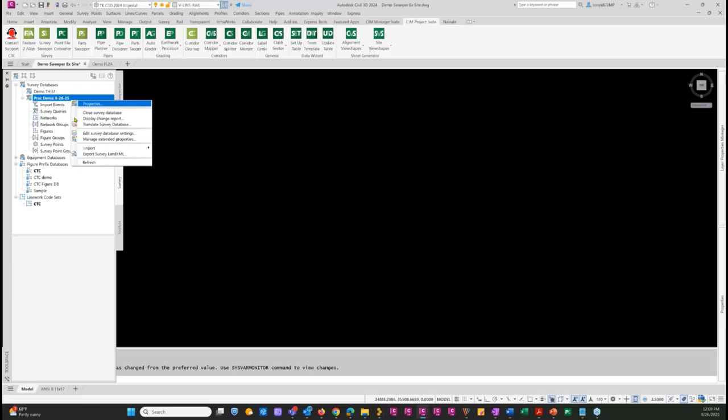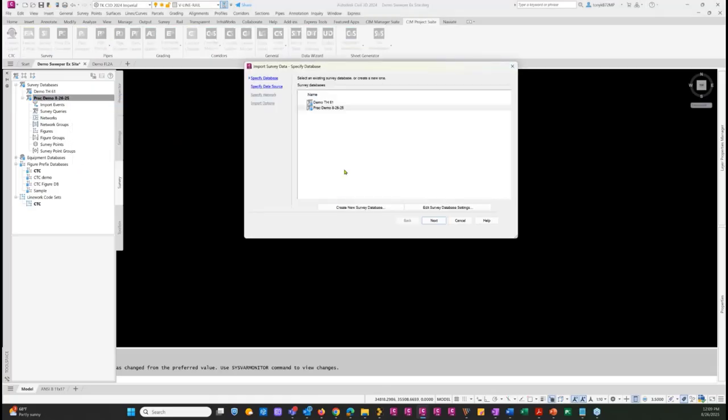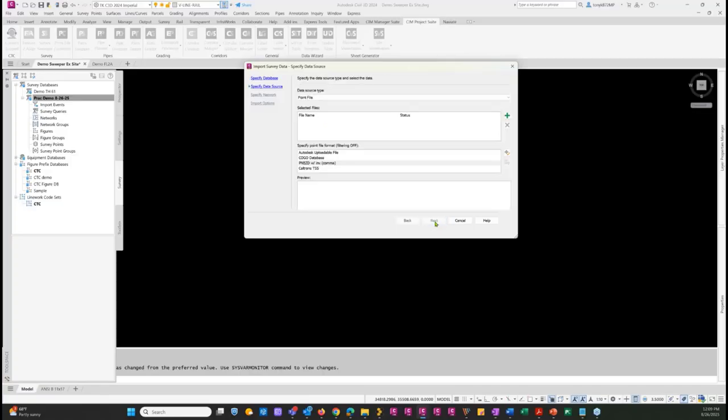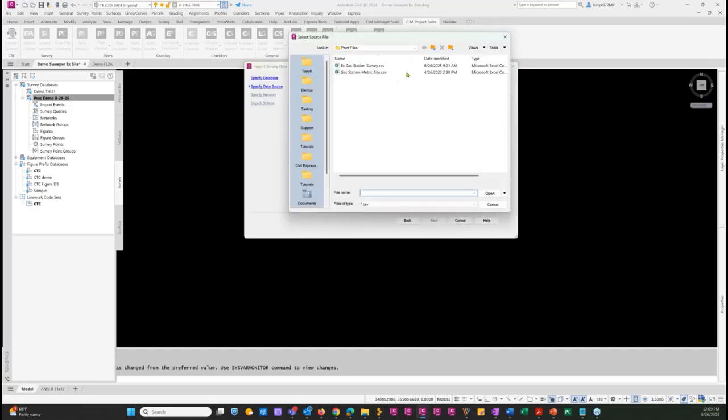I'm going to go ahead and import my survey data. I'm going to set it to that one, and then I'm just going to step through here. I'm going to make sure I'm set to a point file, and I'm going to get my actual point file for this, which is this one.